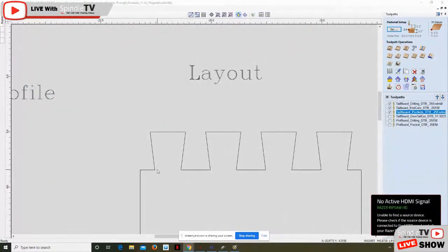On my part, I wanted to start with half a bit diameter. And then I wanted to go equal distance, so each side was half the diameter of that 17/32. So I did half a pin, if you will, and half a tail, whatever you want to call it, and half a tail. And then I spaced them out equal distance.